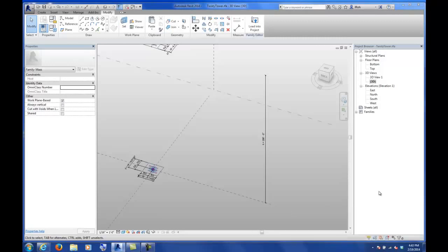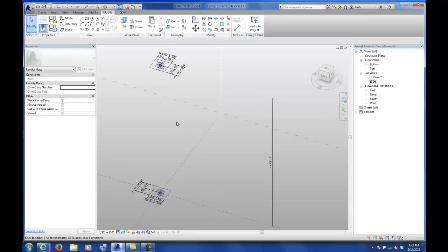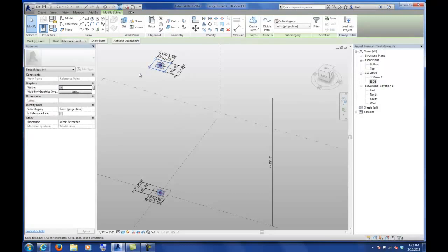Yeah. Okay, everyone listen up. This is important. I actually forgot one little checkbox here. So we've done that alignment. One thing that we have to do when we're starting to actually make solids out of wireframe geometry. Right now, if you click on your wireframe, if it's black, it's basically a black line that goes all the way around. That is called a model line, and that's what we were drawing with. Once you make a form between two model lines, it basically locks it in place to those particular components.